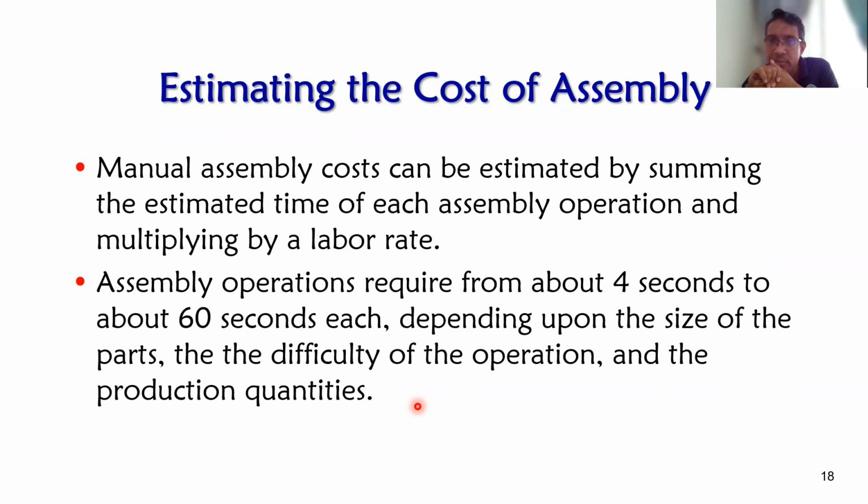All right. At high volumes, a worker can specialize in a particular set of operations, with special jig features and tools that can assist the assembly. So when we want to estimate the assembly cost, we need to do line balancing or take time for the time studies of the assembly process. We need to count the time from the beginning until the end, and then we need to have one unit time for each product.